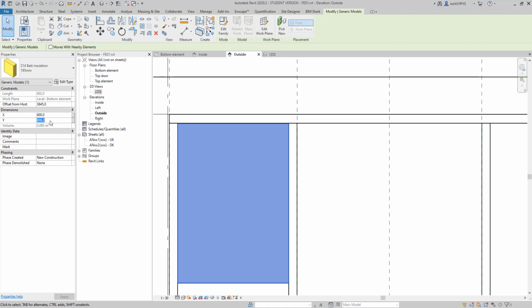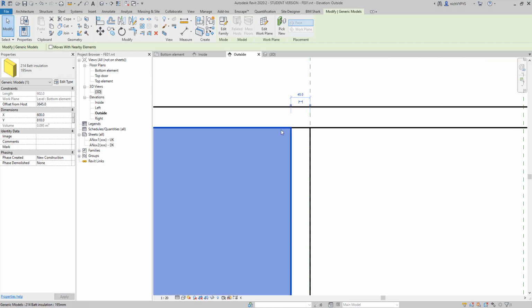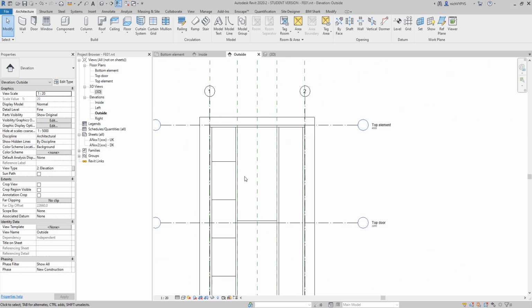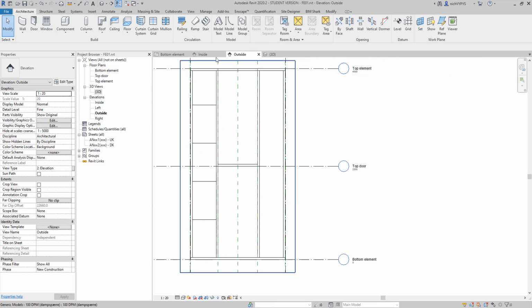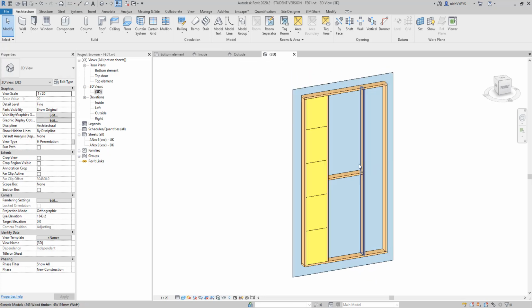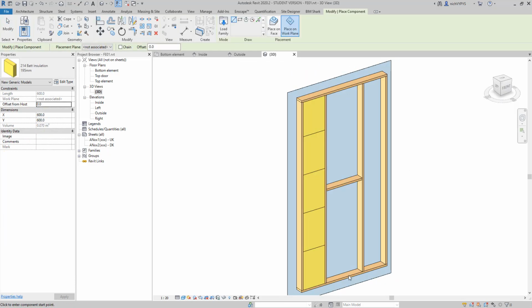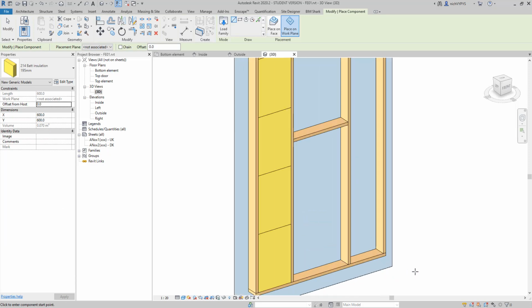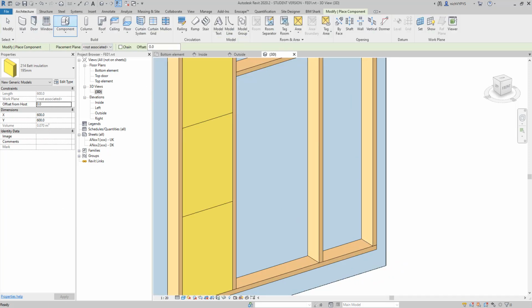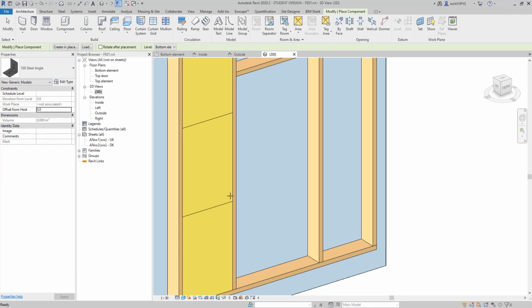As you can see, I cannot snap to the top beam, but since I'm working in precise millimeters, I can adjust it so that I know that the last batt has the correct size. Then I can add steel angle brackets if that is necessary for the project.